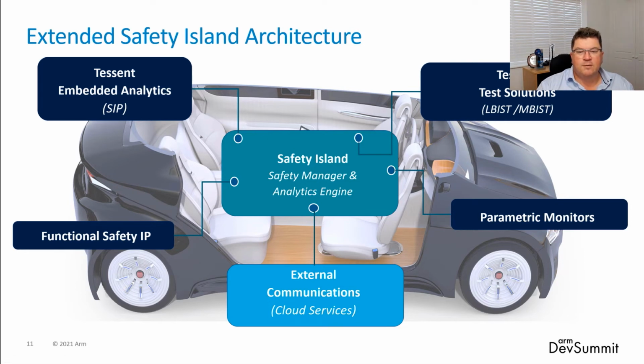So what do we do with all the data once it's collected? Obviously, if there's any immediate action that's needed, for example, if any flags get raised from the functional safety IP, we can have the software instruct the system that there's an issue with a particular part of the device. The same occurs from the test content. If we run any of the structural tests and we detect a defect, again we can raise that immediately to the overall system controller. For the bulk of the data, for which we need to take no action at all, it's possible to make the connection to an external interface. There we can extract the data whenever possible to a cloud-based service, where we can then do deeper analysis on the data alongside similar data collected from a whole number of vehicles out there in the field.